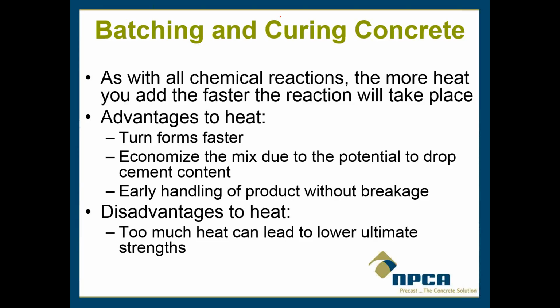There's this nifty little chart that shows the three keys to curing something effectively: time, temperature, and moisture. With proper curing, your strength is going to increase, your concrete will be less permeable, so it's less susceptible to chloride attack or something like that. The concrete will be more durable, more resistant against abrasion. So if you pay attention to the amount of time your concrete is curing, and you apply accelerated curing techniques at the appropriate times, that'll help. That's one of the keys to curing your concrete effectively.